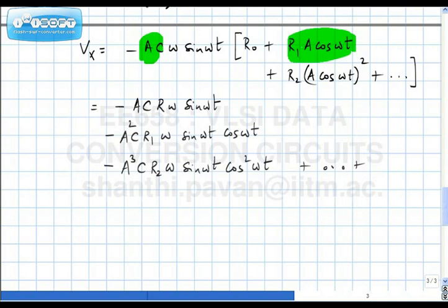For small omega, clearly the bandwidth of the track and hold is basically about 1 over RC. The argument that the input frequency is much smaller than the bandwidth basically means that we can neglect this term. In any case, this frequency is at omega itself, which is equivalent to saying that the fundamental component at the output is almost the same as the input fundamental component, which you knew already.